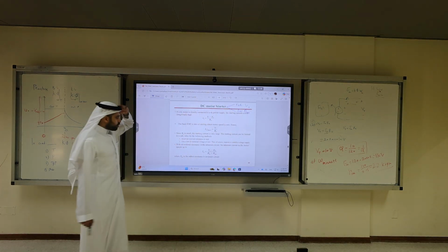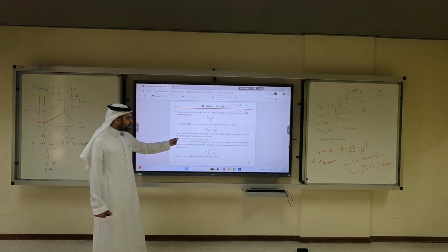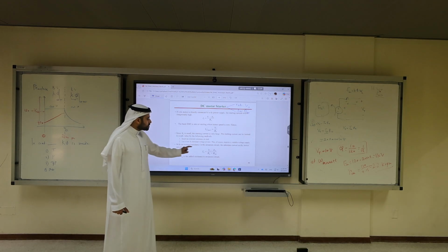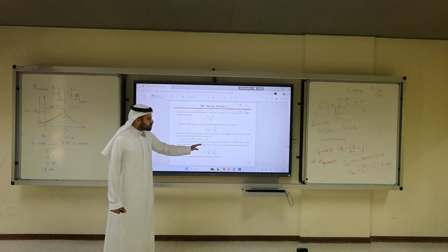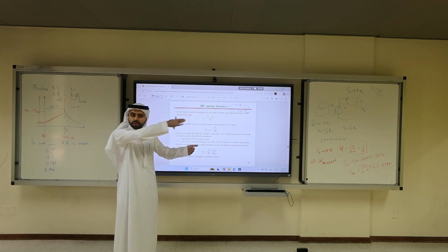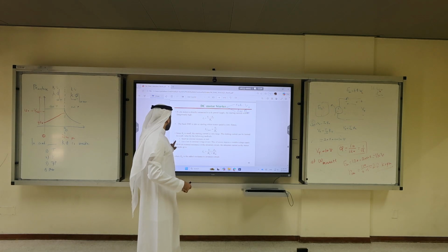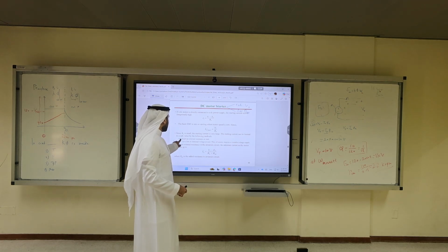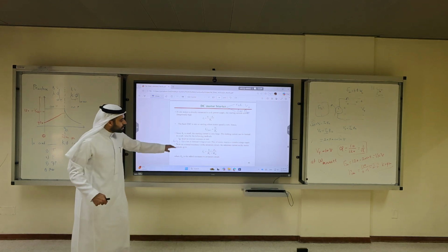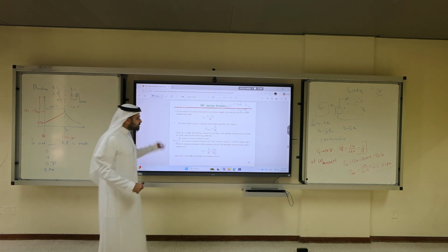So for separately excited motor, for example, we insert external resistance at start, or you reduce the voltage like what we did in the previous example. So we already showed example 9. Here I'm not going to do an example, but if you increase the current, if you don't have power electronics, you can add a resistance.